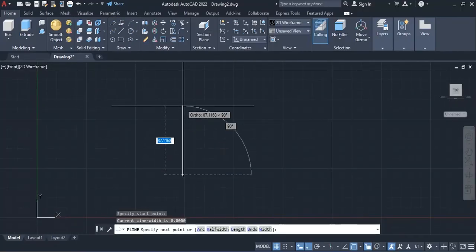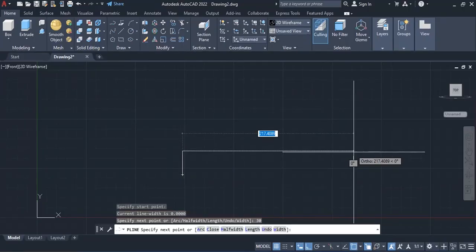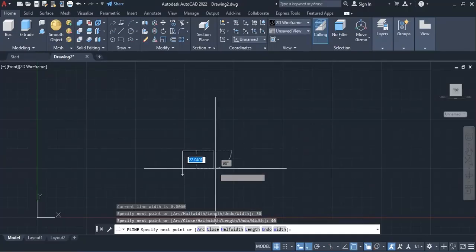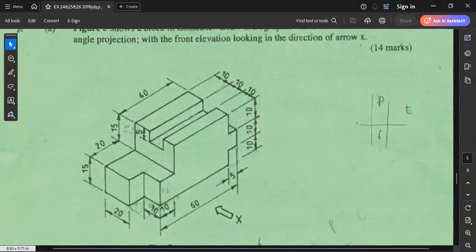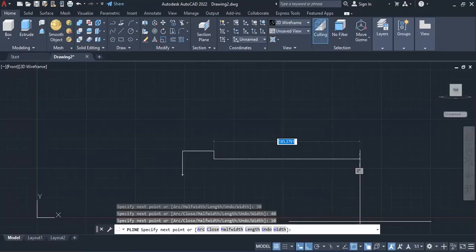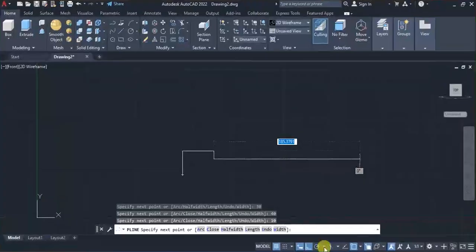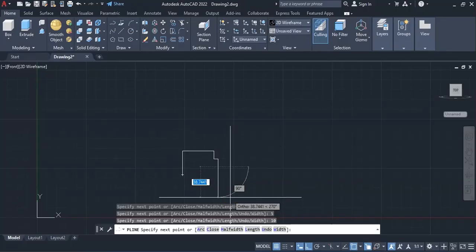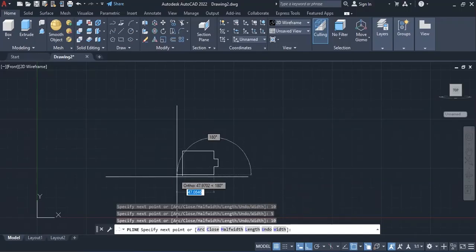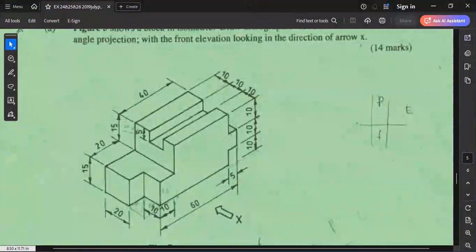Click on the first part, it's too small again, so I'll have to zoom out. So I'll start off with 30, then enter, then 40, then downwards 10, then downwards 10, then to the side 5, to the side 5, enter, down 10, enter, side 5, down 10, then combined to the first point, then enter. So that is the first bit, as you can see.